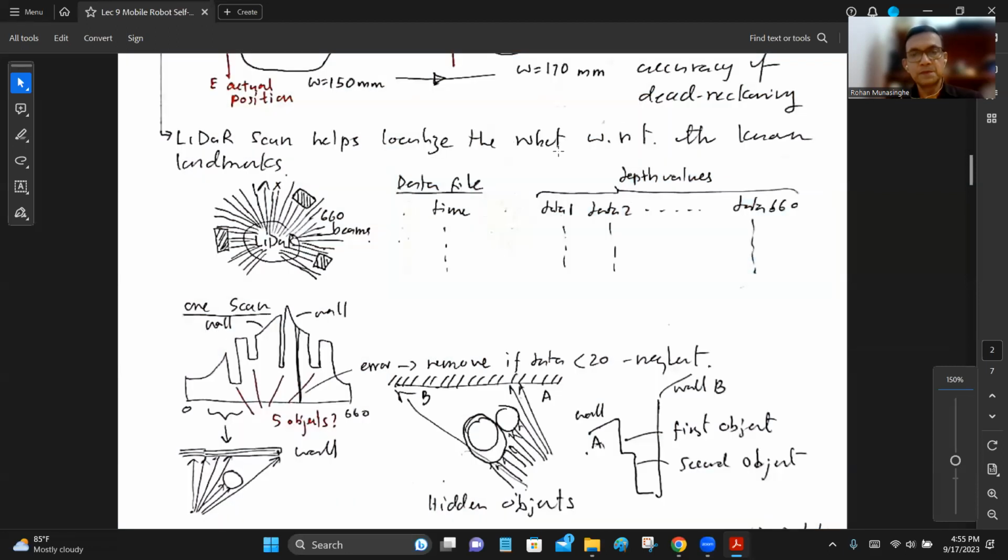When it is scanning a tree, the tree contains a lot of beams. Exactly, a lot of points. Between two beams it's a quarter of a degree, so if you think of a tree nearby, it covers some 3, 4 degrees. Therefore, it easily gets about 10 or more than 10 beams falling on that tree. Then we take some midpoint around it as the coordinate. That's right. You take the midpoint of the beams as your coordinate.